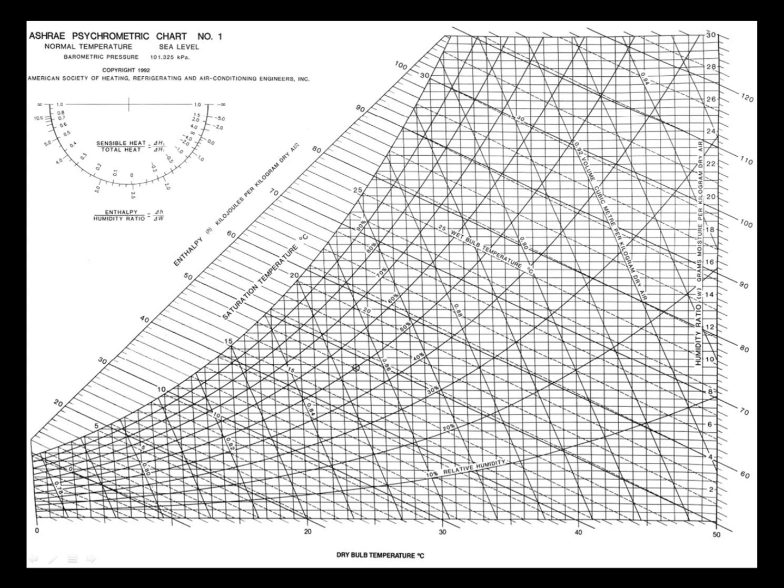So let's go to state 1. It tells us the temperature, and that's dry bulb temperature at state 1, is 25 degrees. So let's draw a line up from there. It also tells us that our wet bulb temperature at state 1 is 10 degrees Celsius. So remember, the wet bulb temperature lines are these diagonal dotted lines, and it's indicated here the value at 10 here. You can use the scale on the left or these scales on the lines themselves. Let's draw a line of constant wet bulb temperature. And where those two lines intersect, well, that's state 1. So let's mark that as state 1.